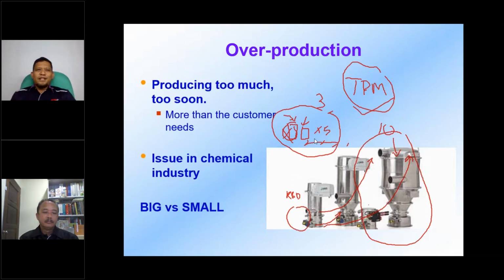The reaction should be much faster. Instead of maybe 6 hours, using a smaller scale it can be half of it, because the temperature can be raised faster, the pressure you can raise faster, and the speed of the agitator is faster. So the reaction time will be faster, and then you can produce more.